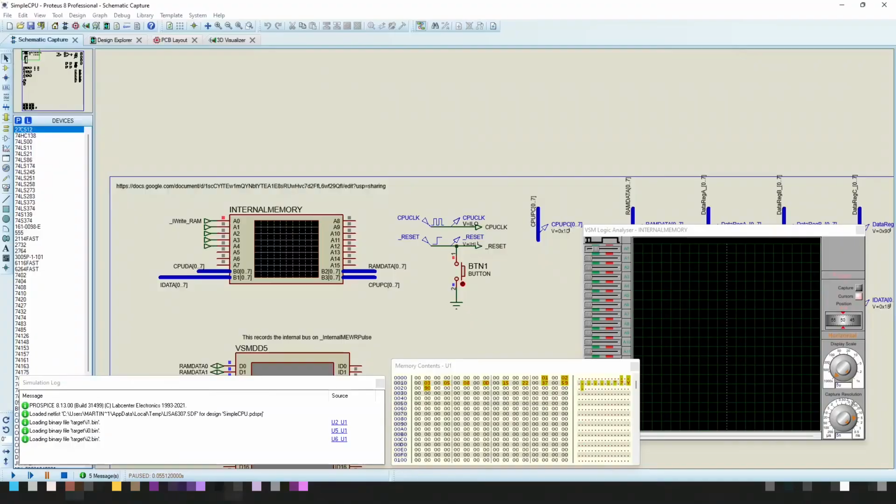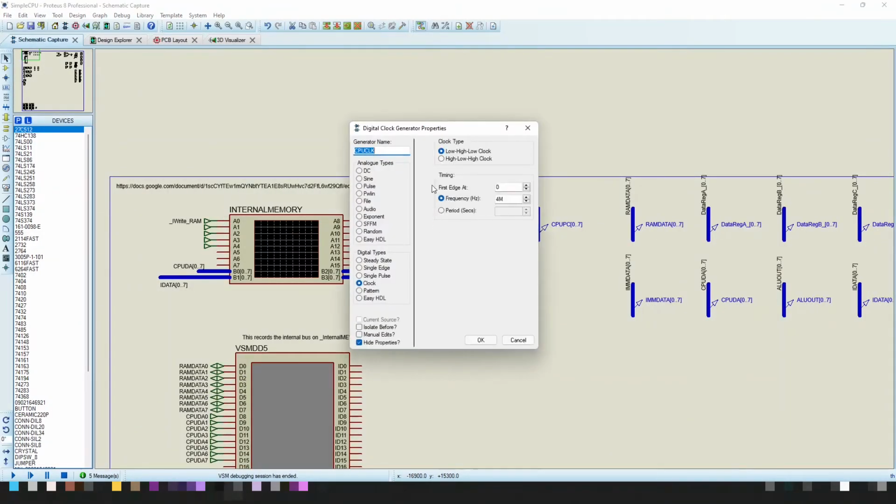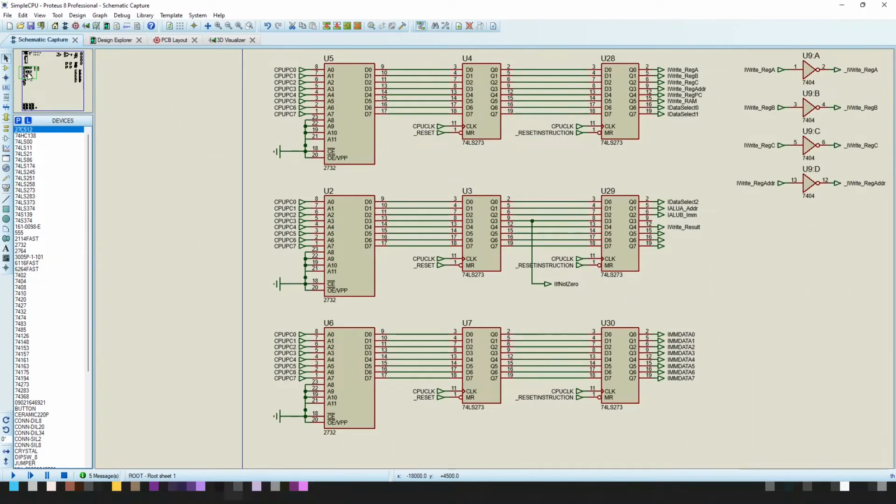That's cool. However, if I crank it up to the theoretical failure point, which is at 5 megahertz, now the simulation, of course, introduces some extra random or pseudo-random latency to all of these signals. It introduces this because it wants to help you produce a much more robust simulated design. So the latency is by default, okay, and I haven't changed the default value.